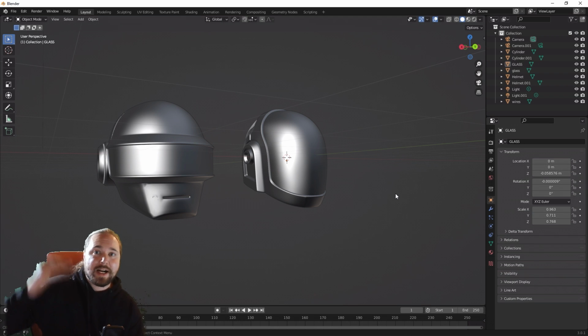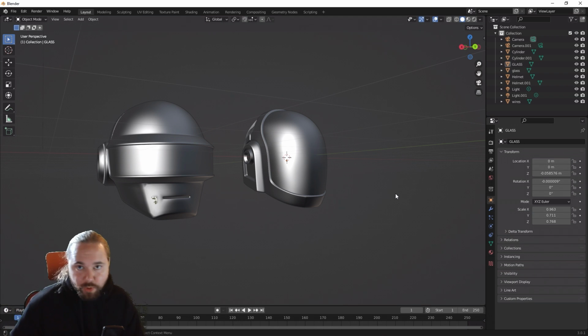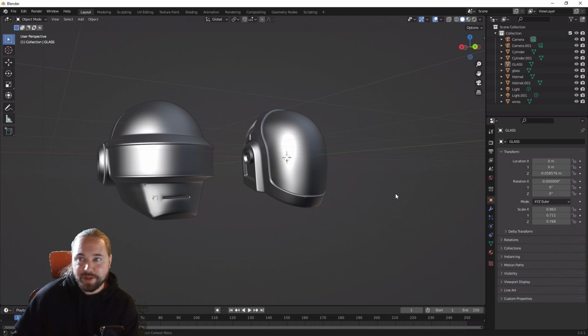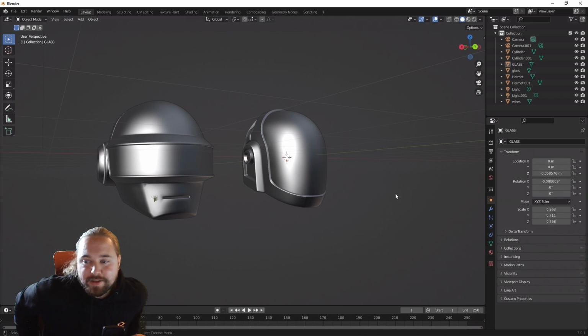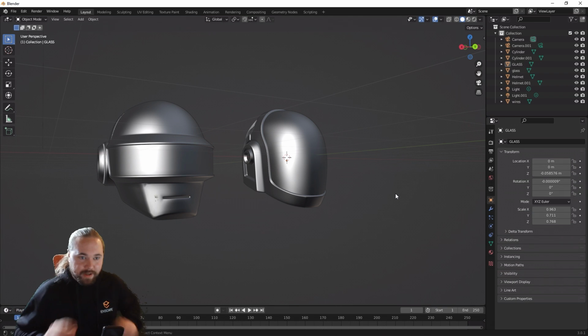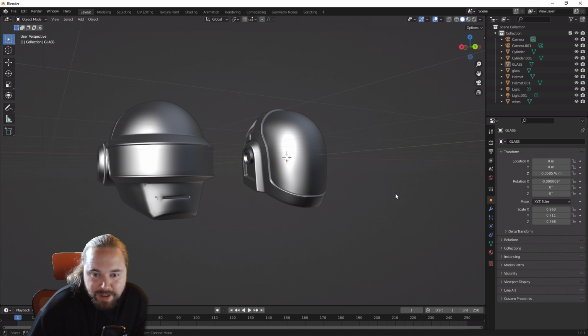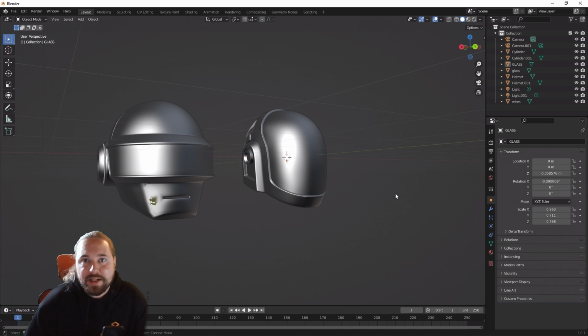There is no maximum cap, but of course, depending on your hardware, depending on the overall scale and complexity of your model, it is possible that if you bring in a model that has 800,000 polygons, it will lead to performance issues. So that's what that warning message is for. In this case, we have 2 models, each of those 60,000 polygons, so we'll have around 120,000 polygons in total. I will still bring this into Enscape.